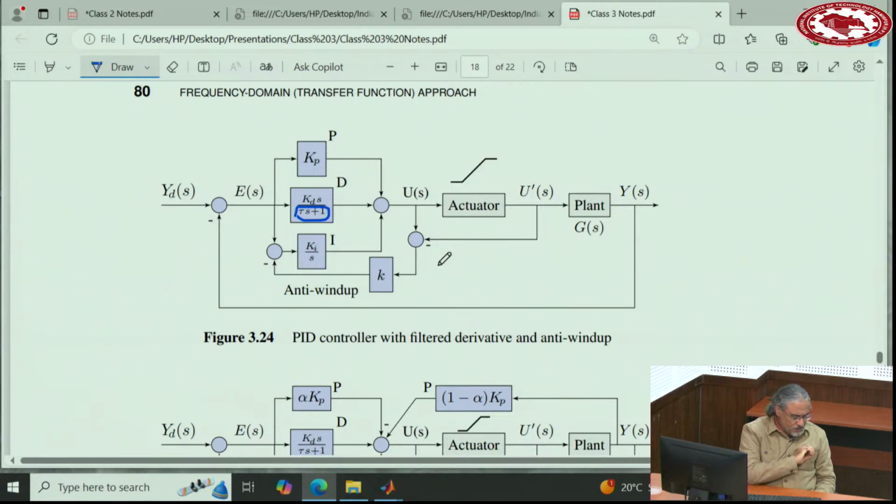So if you push the system, or push the response of the system or the operation of the system, to the limits, it will actually cut the signals at that point. It cannot generate more than 400 volt. If the controller asks the drive to generate 500 volt, and its limit is 400, it cannot generate more than 400. It stays there. So it's just like a model like this.